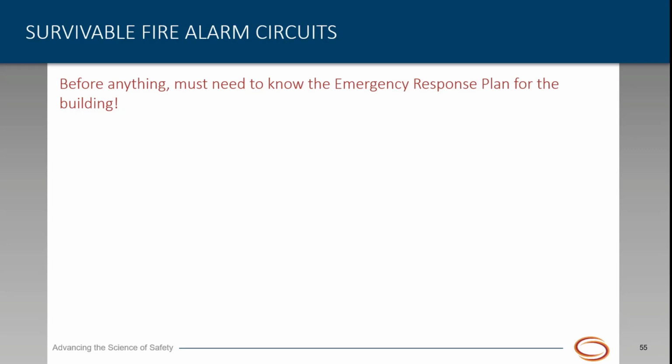Well, obviously that's not happening in a normal course of events. We have to know what the evacuation scheme is. Is it a general alarm building? Because if it is, then we're done from a survivability standpoint. However, if we assume it's a general alarm building and it turns out not to be, then we're in for some very expensive rework, change orders, and probably liquidated damages.